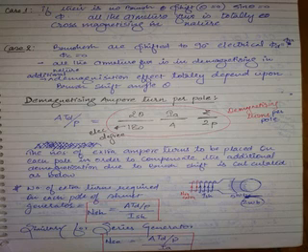So what is the unit of this? Ampere turns per pole, right? So this is ampere turns per pole. I am writing this simply as AT_d per pole. Now, you know ampere turns. If you want to derive turns from ampere turns, what you have to do? Divide by amperes. I'm repeating again. There are ampere turns here. If you divide it by amperes, what you will get? Turns. What you are adding on the pole? You are adding turns. What do the amperes mean? Already there is field current flowing in them.